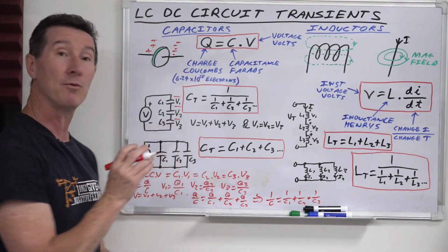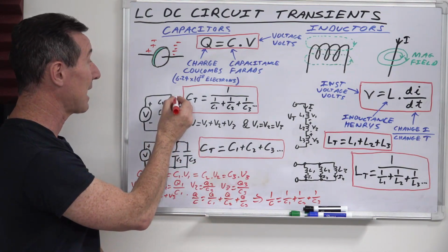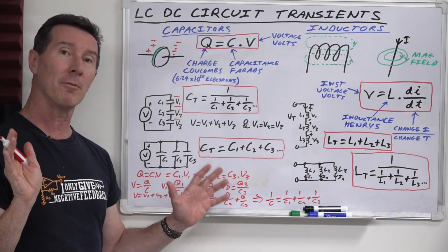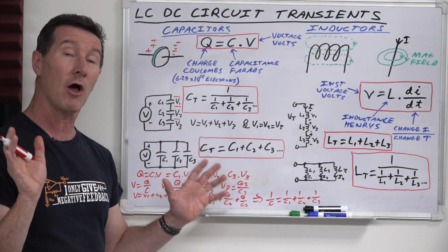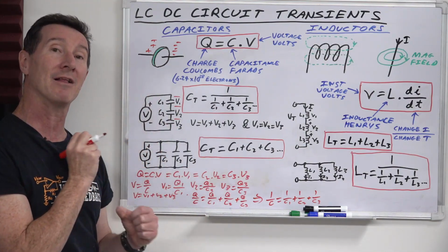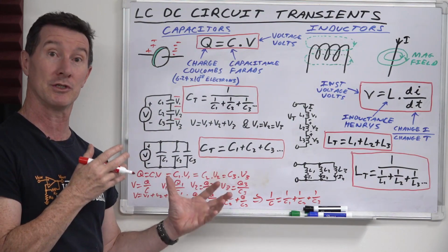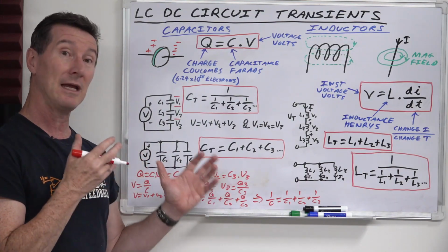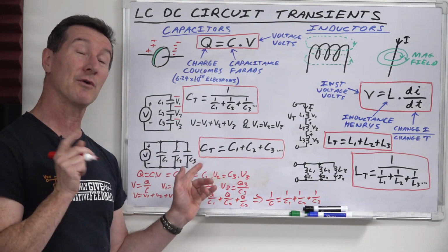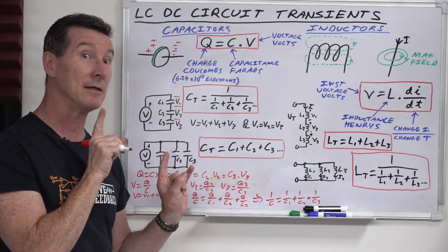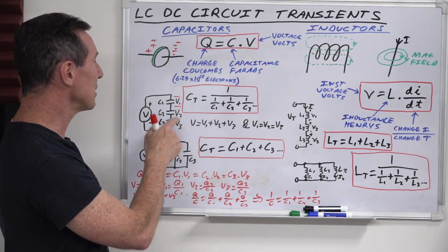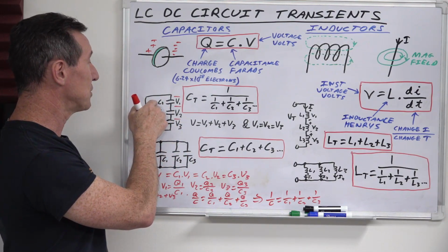Sometimes you'll find what are called balance resistors in parallel with series capacitors like this. You'll find these commonly in high voltage power supplies and things like that, to help balance out the capacitors due to practical differences in the capacitors. So anyway, that's just a useful thing to know. And it also helps discharge them as well. Handy.